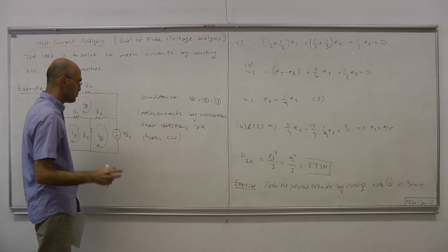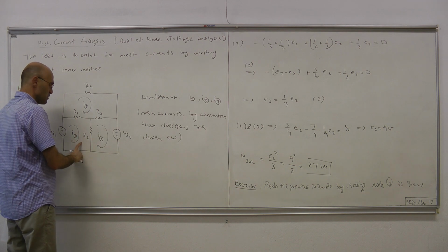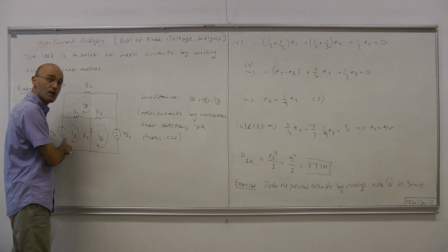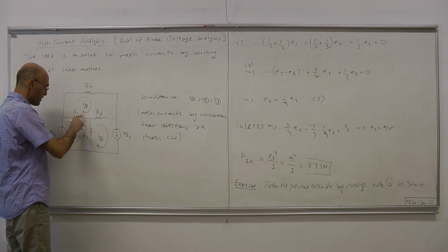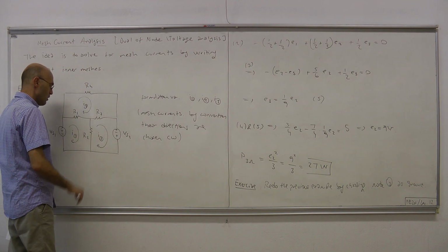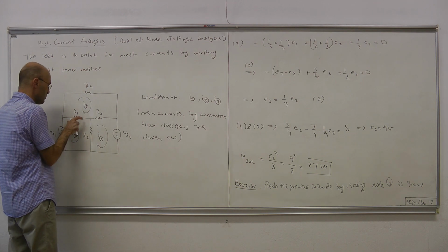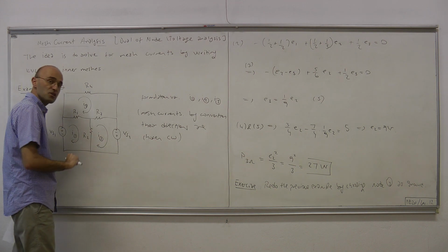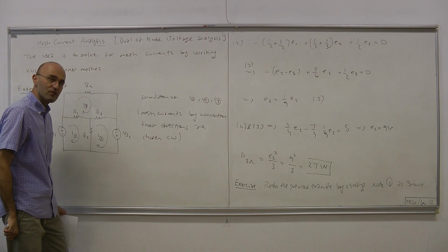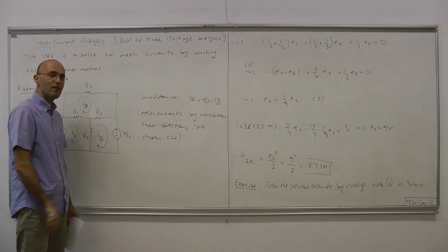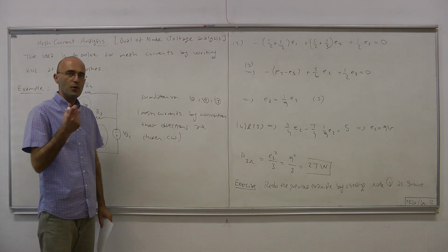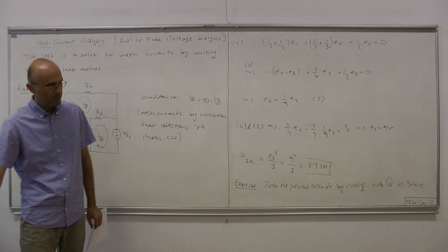Now, once we have the proper labeling, we'll write KVL at each mesh. Writing KVL at each mesh means that here is a mesh, and to this mesh there are 3 components associated, R1, R2, and this voltage source. As we go along the direction of the mesh, we sum up all the corresponding voltages, plus minus VR1, plus minus VR2, and finally plus minus this voltage source VS1. That sum, because it's a closed path, a loop, by KVL must equal 0. And that's how we obtain the equations.